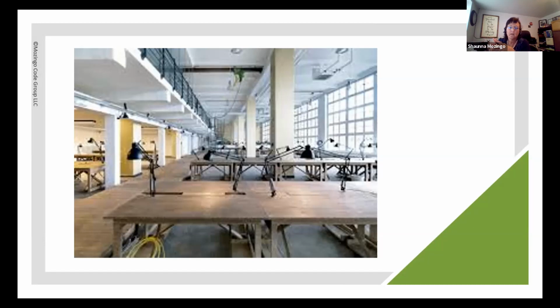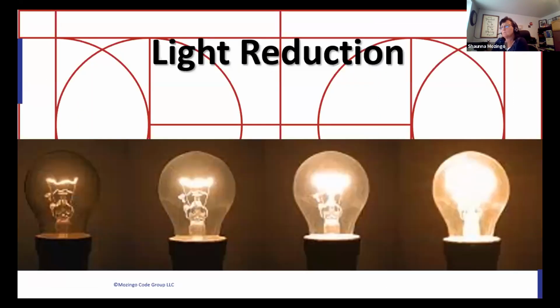And then number 4, the requirement was revised to say that general lighting in each of those control zones has to turn off uniformly or reduce the lighting power to an unoccupied set point of no more than 20% of full power within 20 minutes. So just fine tuning it. Again, it came in 2018, just going to keep fine tuning those requirements.